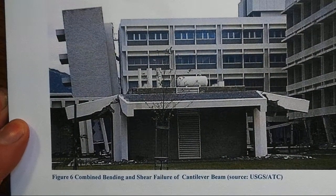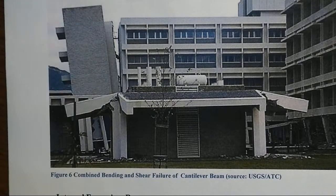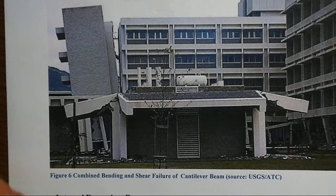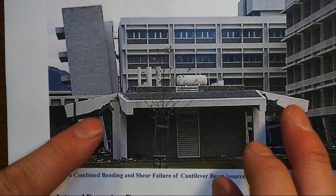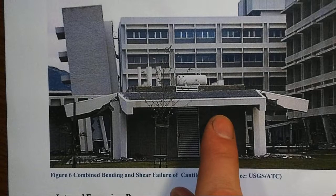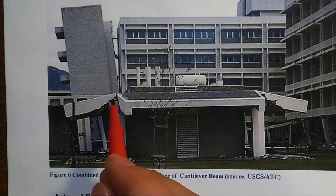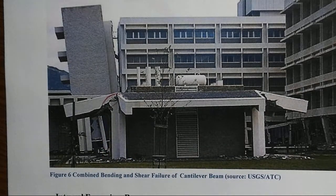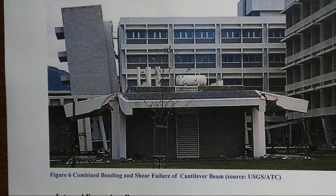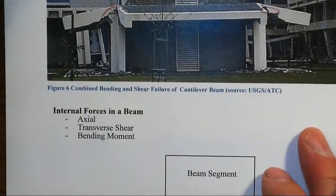Here you might get distracted by this elevator tower that has had problems and rotated in a global way, but sitting in front of that is this small one-story building that has these cantilever segments that are just aesthetic. They're canopy type situations, and they have failed right in this area, the beam column connection point, in a combined bending and shear kind of failure mechanism. This was an earthquake that caused that particular building problem.